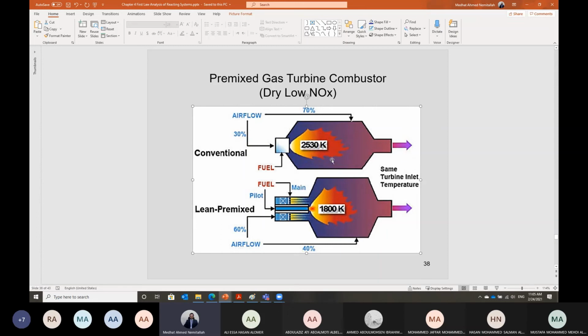For a gasoline engine, it should work near stoichiometric. Lambda should be very close to 1. It cannot go away from 1. But for this gasoline compression ignition engine, in which we use gasoline in a diesel engine, it works at higher compression ratio and at very lean condition. In this case, we provide much excess air. Lambda in this case can approach a value of 300% theoretical air, or even more, in order to lower the combustion temperature, and then we can lower the exhaust emission.